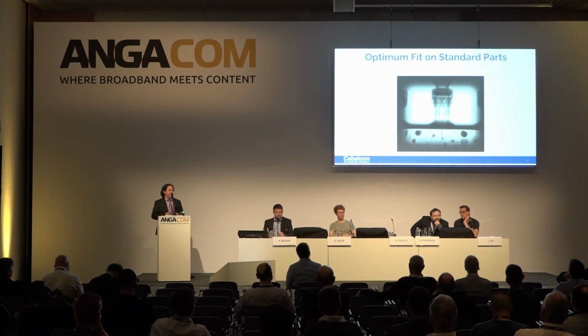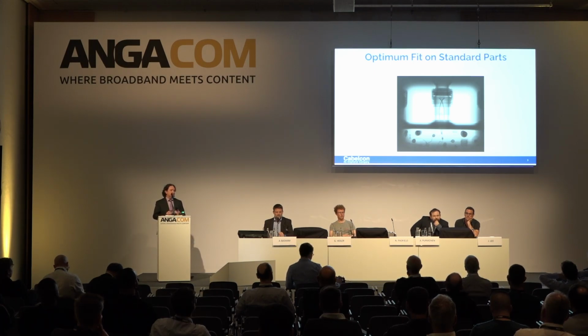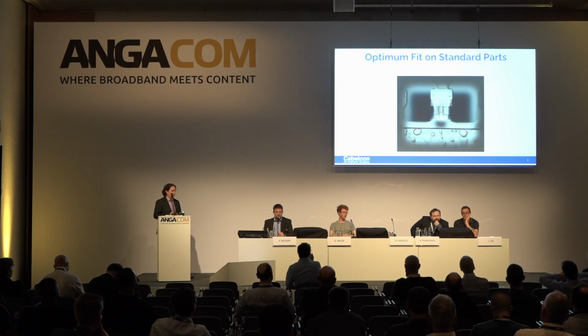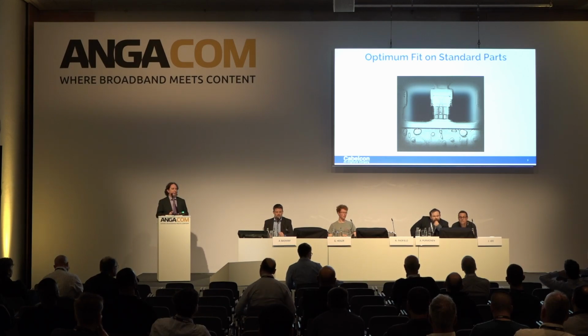Here we have an X-ray of what we'd all hope to see with every F-connector connection: a perfect port with a nice RF flat face, and a connector with well-defined threads on the port and nice well-defined threads on the nut connecting it. Over the top, I've added a bit of a filter just to try and highlight what's going on. This is what we'd like to see on every tap or every RF connection that's out there.